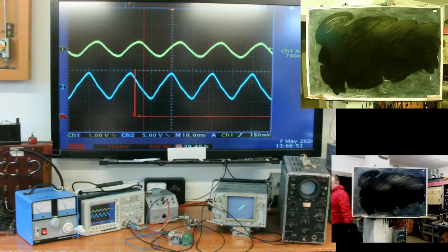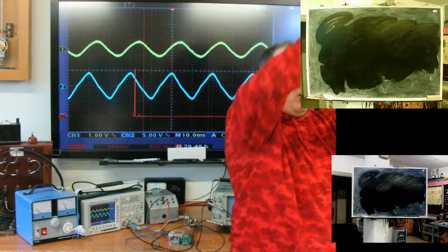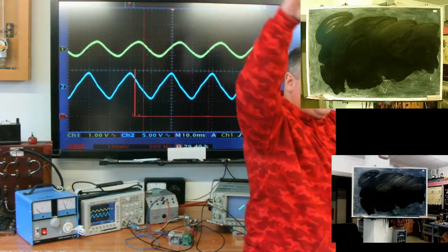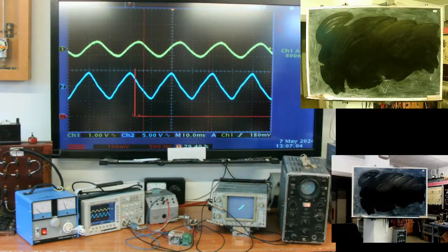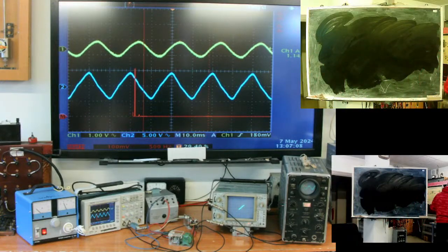After I remove this 150 Hz component from the primary current, nothing compensates the nonlinearity of steel. If it were an air transformer... air transformers do exist. Where is my air transformer?